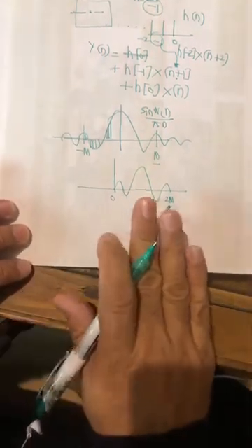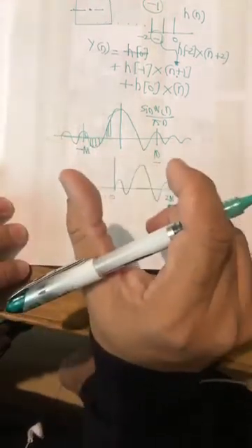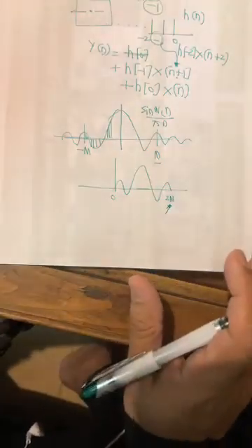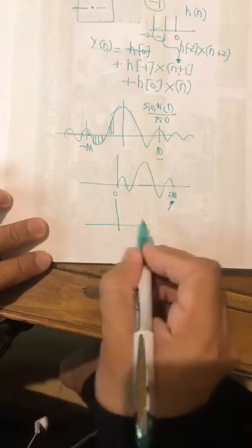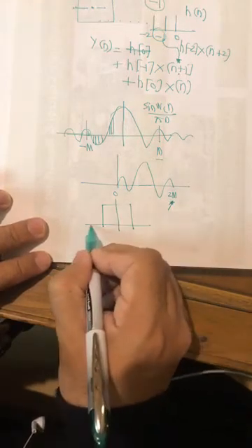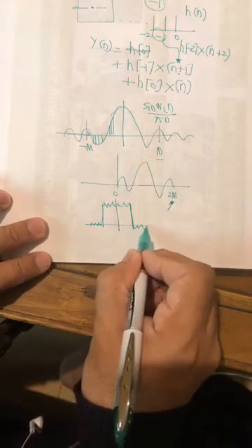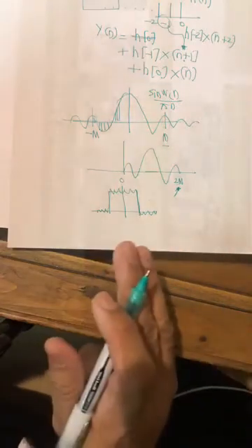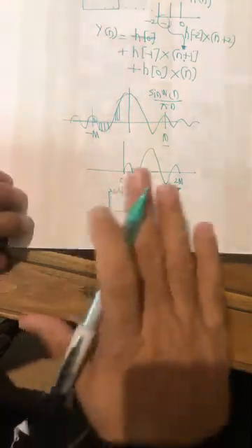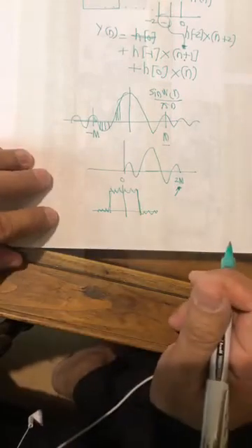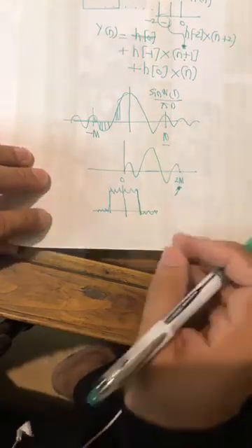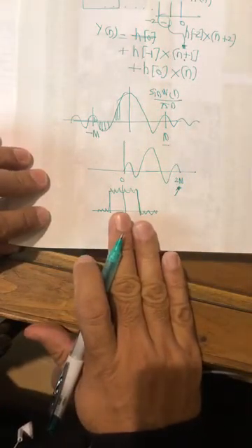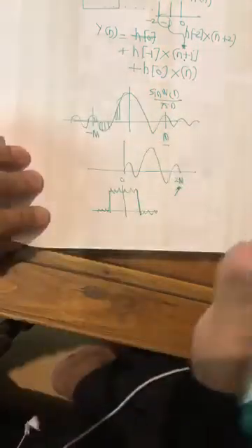If you look at this in the frequency domain, remember that a shift in time would not cause any change in the frequency content, because we know the property. So the magnitude of the Fourier transform is not going to change. The magnitude of the Fourier transform would still be something like this. It is only the phase, and usually we don't care. So you are disrupting phases, and you say, okay, I'm doing something with the phase, so I can live with that. This is the ideal response, and then you shift, and the shift would cause